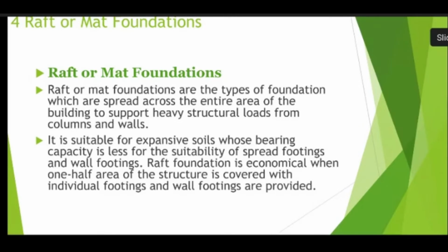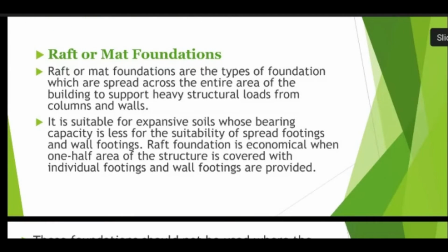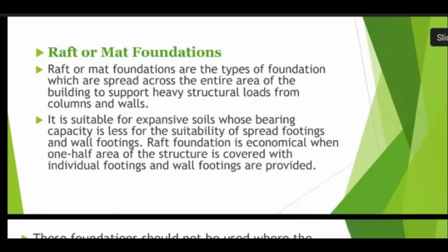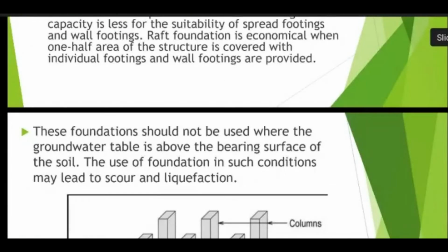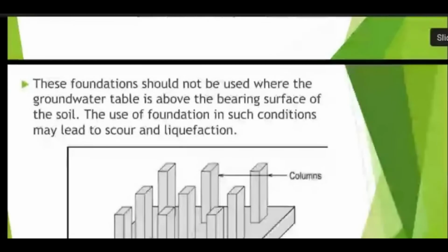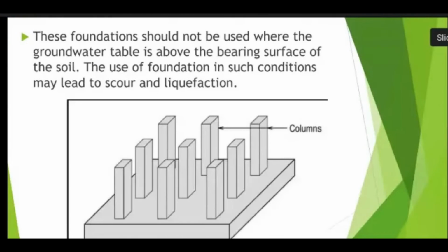Raft foundation is economical when one half area of the structure is covered with individual footings and wall footings are provided. This foundation should not be used where the groundwater table is above the bearing surface of the soil. The use of foundation in such condition may lead to scour or liquefaction.